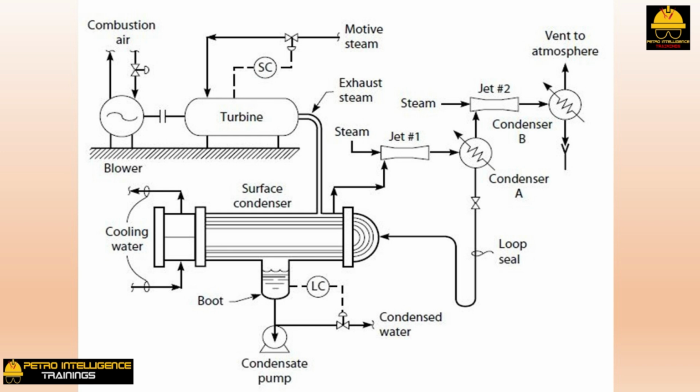For a surface condenser to work properly, non-condensable vapors must be sucked out of the shell side. This is done with a two-stage jet system, as shown in the picture. When he first commissioned the jets, they were unable to pull a good vacuum. Moreover, water periodically blew out of the atmospheric vent. He found, after considerable investigation, that the condensate drain line from the final condenser was plugged.